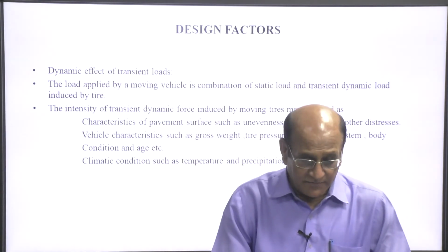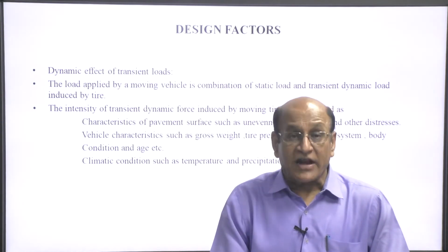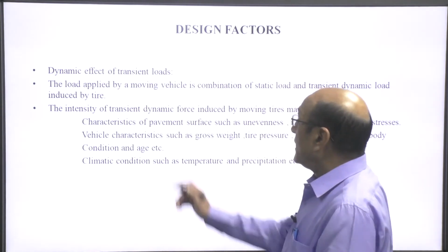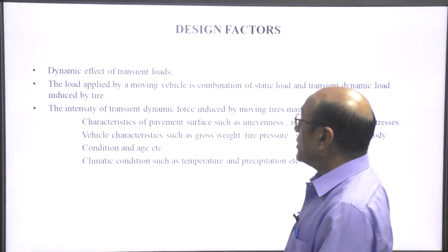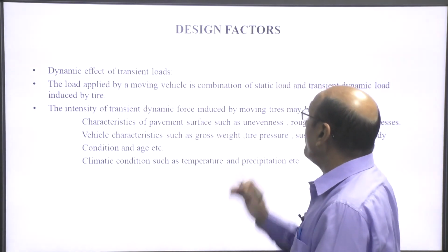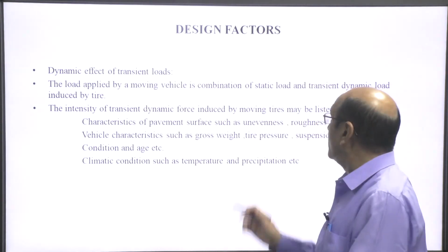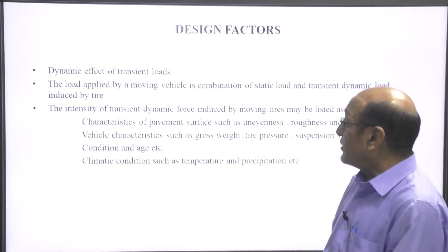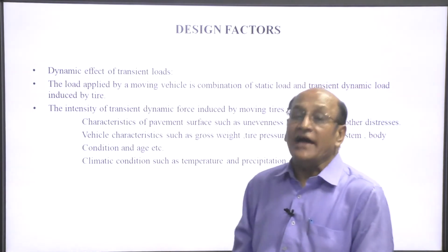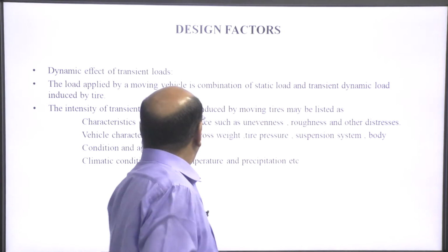Now, design factor: dynamic effect of transient load. The dynamic effect of transient loads applied by a moving vehicle is a combination of a static load and a transient dynamic load induced by the tire.